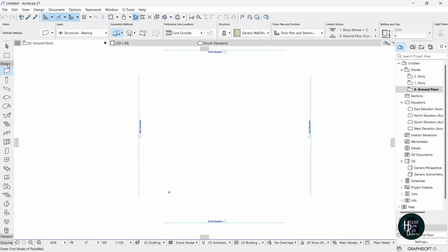If you click on the design tab, you click on the wall tool. Okay, this is a wall tool. You want to hold this down and select this icon right here. If you're having this icon, I want you to change it. So if you hold this down, I want you to select this icon right here. Click on it, and that's going to give you this chained type look. Okay, this is what I'm talking about. It's going to give you something like this.